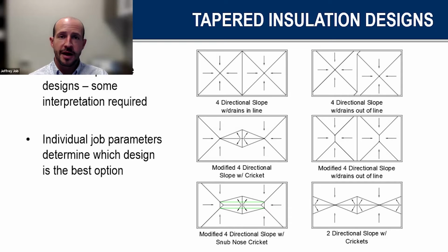One way we typically do that is sloping the roof deck. Code's going to require typically a minimum of a 1/4 inch slope. Some municipalities, greater. So that said, we have to have some type of slope to the roof to allow water to drain off that system.